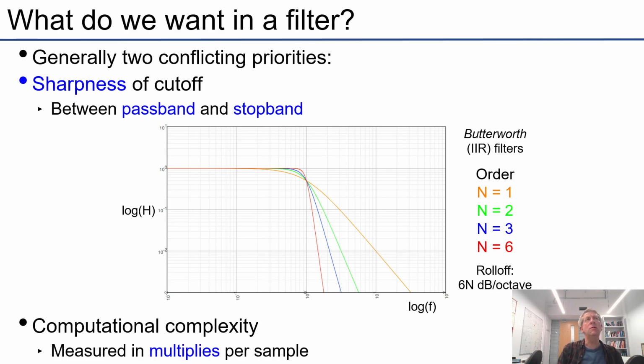If one is dealing with aliasing issues where there are high frequency components in a signal sampled at a certain rate, they can alias back and appear as audible lower frequency components simply because the way in which the audio is represented can't distinguish between the two. That's something we don't want. And so there we would like a filter that completely, or as much as possible, removes these high frequency components.